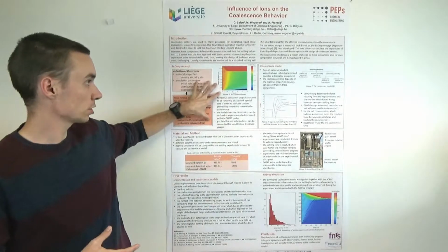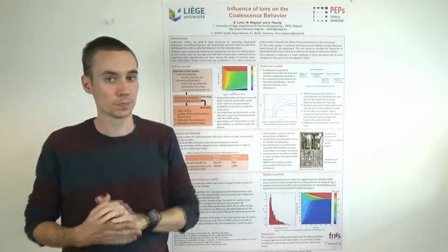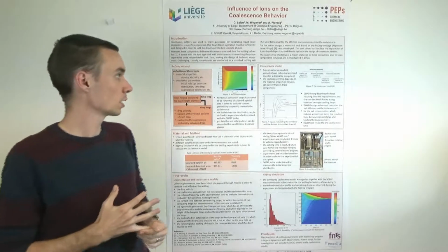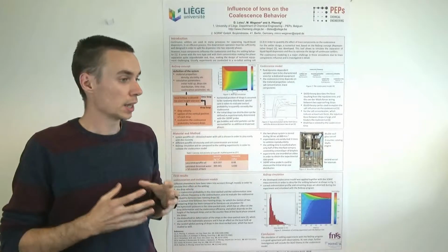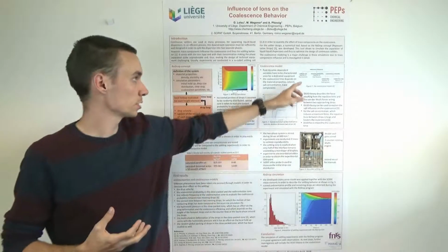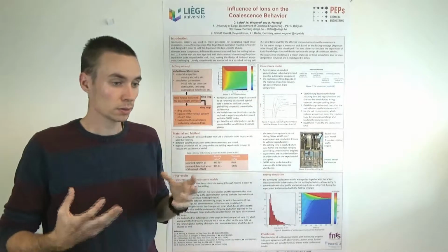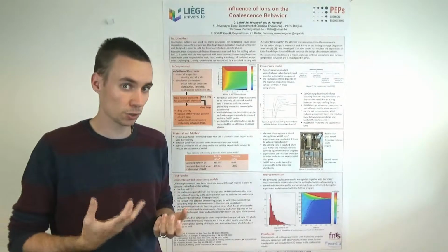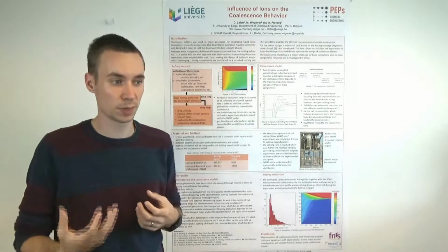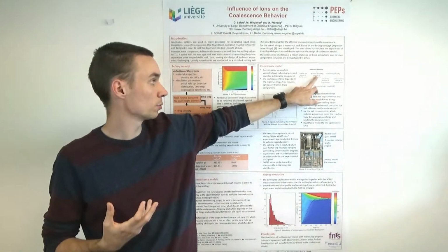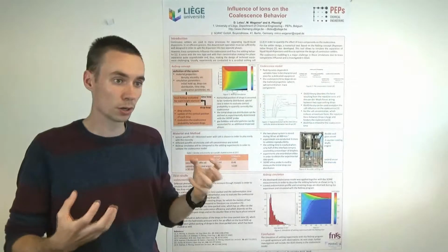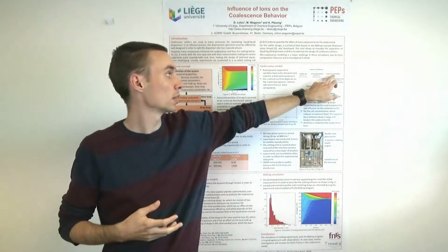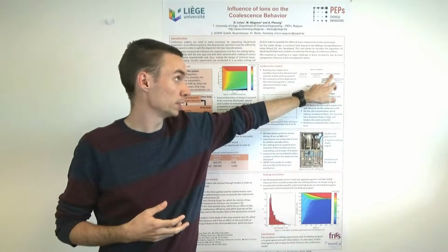Inside my simulation, I have my coalescence model. This coalescence model is based on the observation made by Camp and Kopriva. When the drops settle, they have a certain chance to enter in collision. This is characterized by the collision rate. Then, when they enter in collision, they can bounce if the relative velocity is too high. In this case, I assume that coalescence cannot take place. So you have the second parameter, which is the bouncing probability. If the drops enter in collision and don't bounce, they have a chance to coalesce. This is characterized by the coalescence probability.